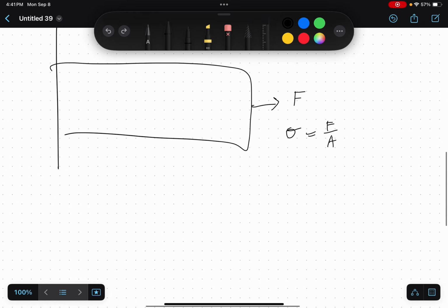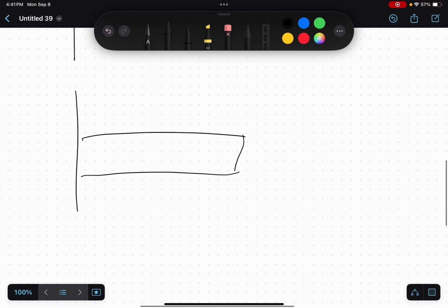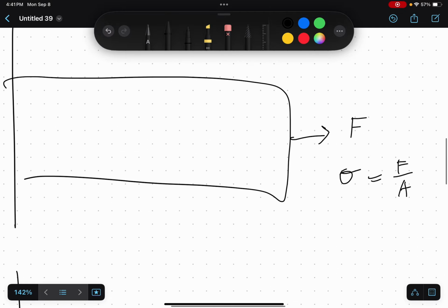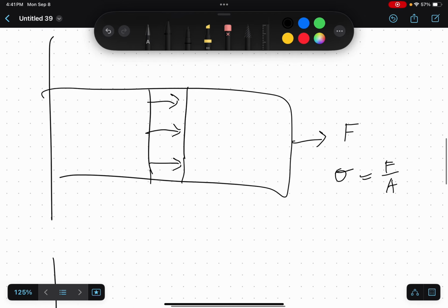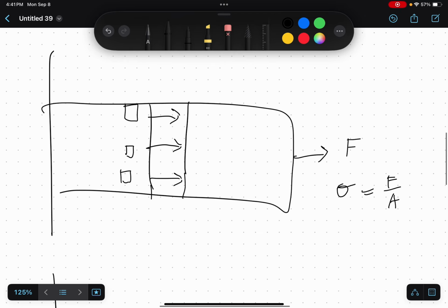Okay, the second type of stress is same beam on the same wall, although it looks a bit different. Let me draw this out also. It would be a uniform stress, and its profile would look like that. So regardless of the height that you're at, regardless of where you draw the stress element, if you draw it right there, or right in the middle, or right at the top, all three of those stress elements would have the same normal stress pointing this way, the same magnitude of normal stress pointing that way.